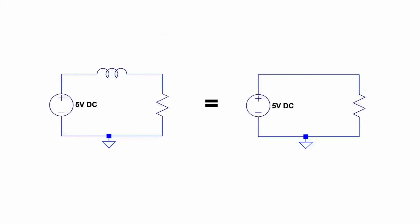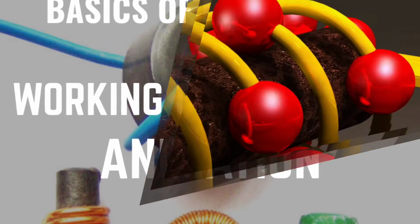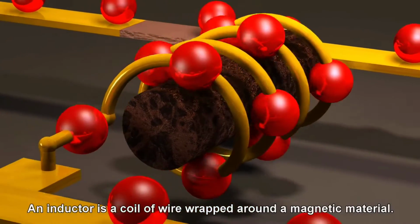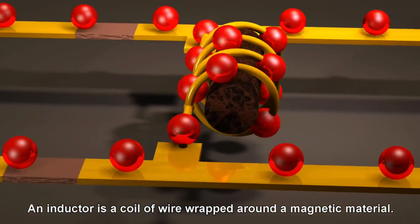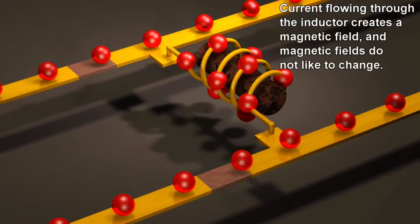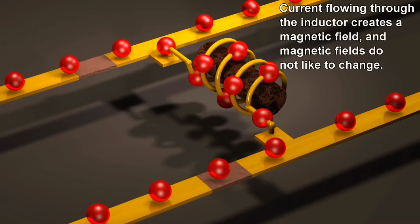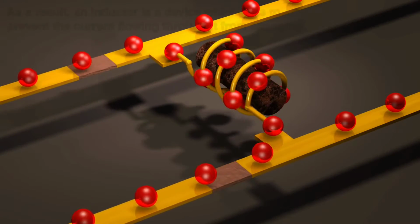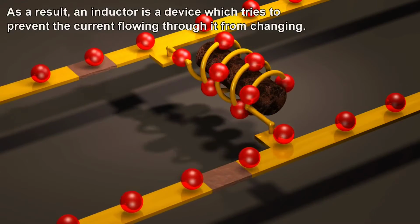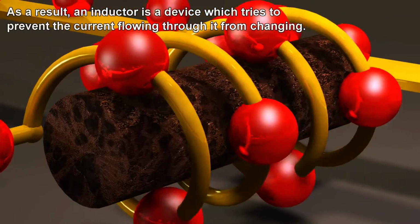Finally, inductors have almost no effect on DC. They're basically just pieces of wire with a resistance of a few milliohms. An inductor is a coil of wire wrapped around a magnetic material. Current flowing through the inductor creates a magnetic field, and magnetic fields do not like to change. As a result, an inductor is a device which tries to prevent the current flowing through it from changing.